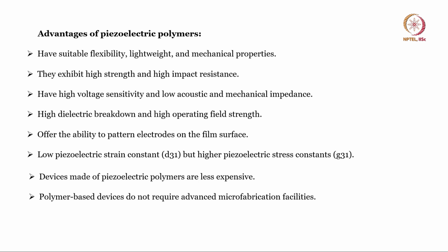Next coming to the advantages of these piezoelectric polymers. As they are basically polymers, they combine the advantages of the piezoelectric effect as well as the polymer structure. That is why they have very good flexibility, are lightweight, and have good mechanical properties. Along with that, they exhibit good strength. The strength of the material, depending on the polymer, will be very good, and they also show high impact resistance. These materials are highly sensitive to voltage, and they also show low acoustic as well as mechanical impedance.